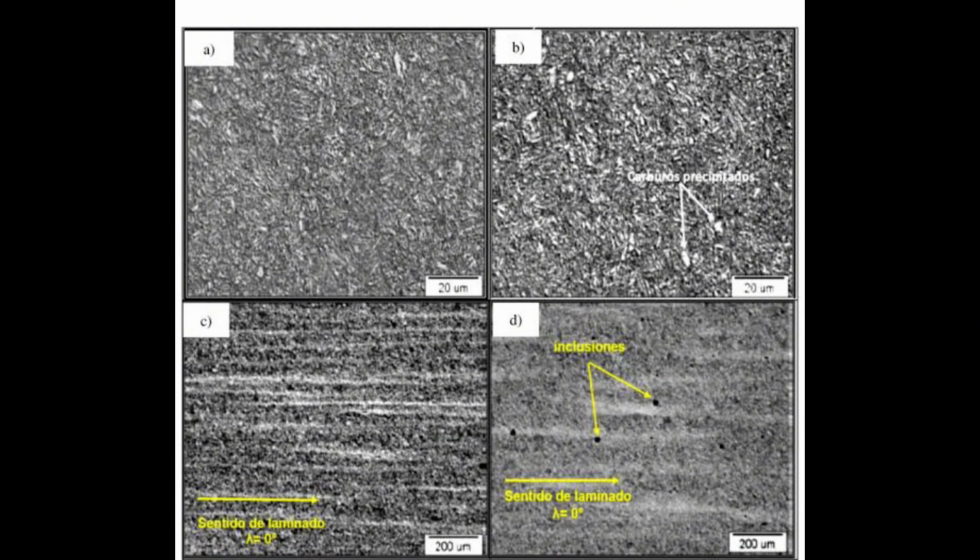Microstructural change. As quenched, martensite is initially hard and brittle. During tempering, excess carbon precipitates. At low tempering temperatures, tempered martensite and fine epsilon carbides form. At moderate temperatures, coarse carbides form and the lath structure relaxes. At higher temperatures, martensite reverts to ferrite plus spheroidal carbides. Overall, there is a transition from hard, stressed martensite to a more ductile structure with distributed carbides.